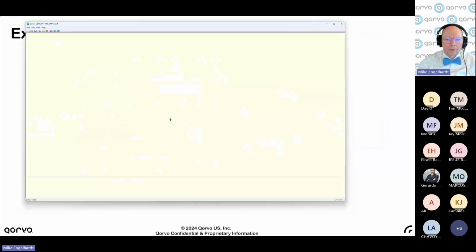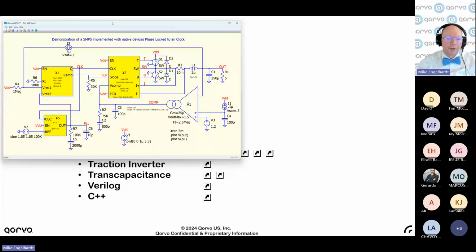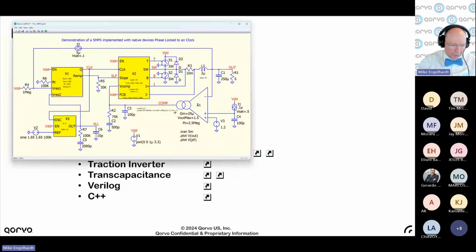This is basically a Linear Tech style switcher. Linear Tech really made a lot of money off of a current mode DC to DC converter. Okay, so they were current mode. They used true high side current sensing. They used quadratic slope compensation and frequency foldback. That was the archetypical Linear Technology product, and that came in all different current handling capabilities. They made thousands of those things, thousands of different designs. And this is basically that system.